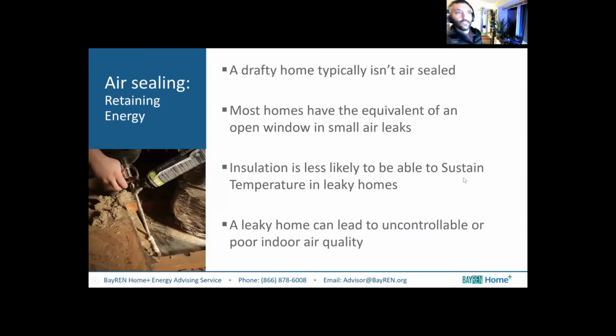Air sealing, the majority of it is done through caulking, spray foam. Mastic is my favorite. Mastic and fiberglass tape is a great combination. It stretches, expands in California for earthquakes and for leaky houses.